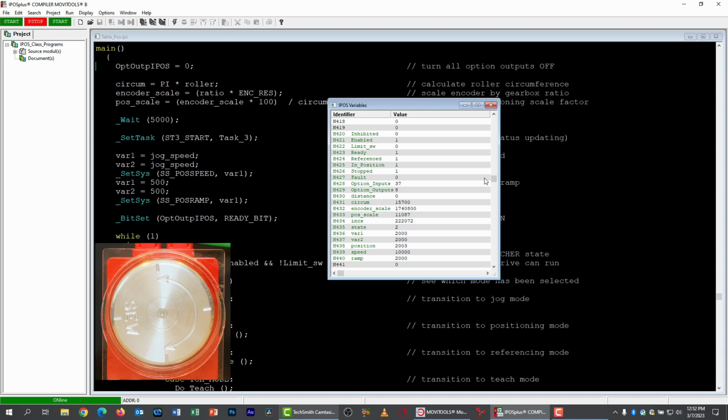And we're now going to test the limit switch. I'm going to take off DI4. So here we go, position. Trip the limit switch. We have that and a fault. I'll turn the limit switch back on, and then I'll clear the fault by turning DI07 on and off. And that cleared the fault. I turned DI12 off, so it's not going to resume positioning, but I can just trip DI12 again, and it'll finish the positioning operation just fine.